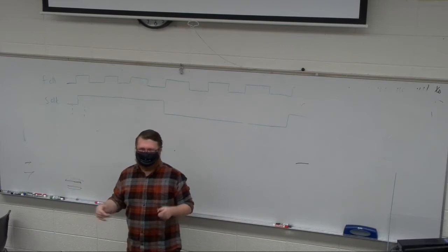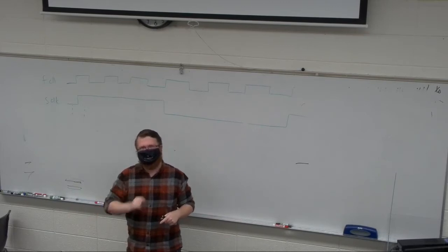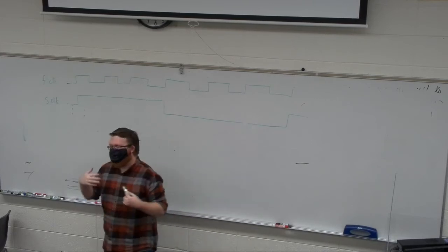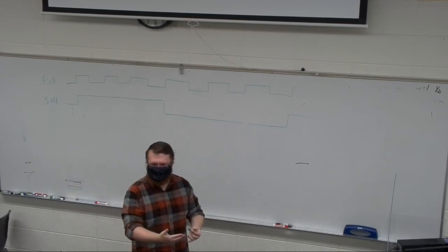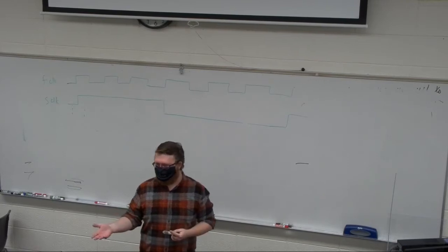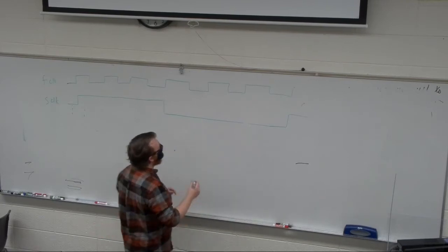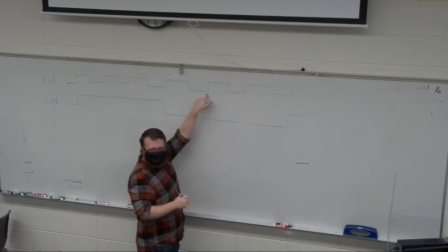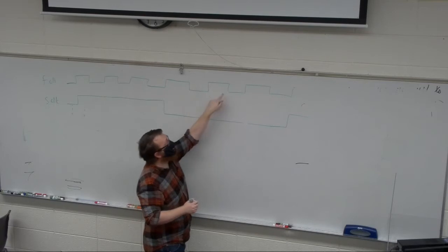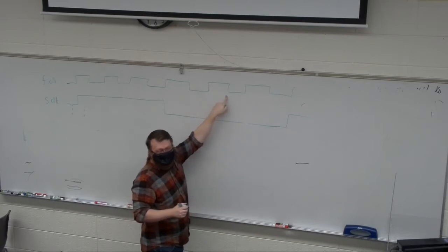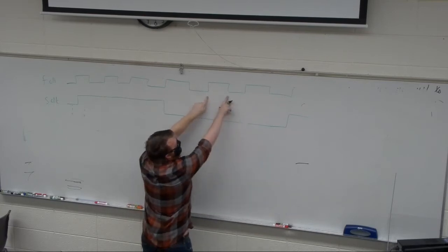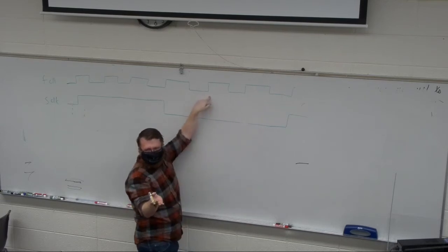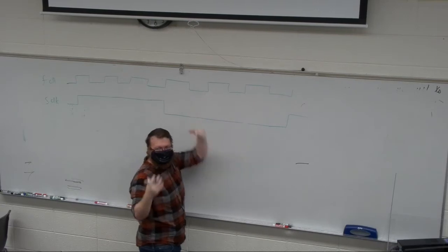So clock drift, I believe I mentioned this a week ago, maybe a little longer, is the idea that as I start putting out packets of data, in the case of UART, I'm trying to start by transmitting in the middle of one of these bits, and then we update on the following edge, right? And if we start to drift, we can drift an entire half a clock cycle minus the setup or hold time before we have an error.